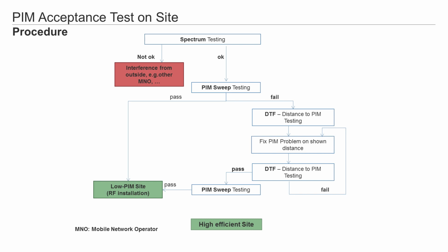If the spectrum analyzer shows interfering noise, the antenna should be disconnected and the transmission line terminated with a low PIM load. Stressed PIM testing, or testing with CW power, should be carried out. It is only with CW power testing that the transmission line is loaded in the same way as the BTS will be during subsequent operation. Only stressed PIM testing ensures high quality and reliable installations.